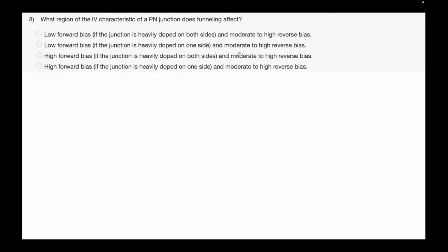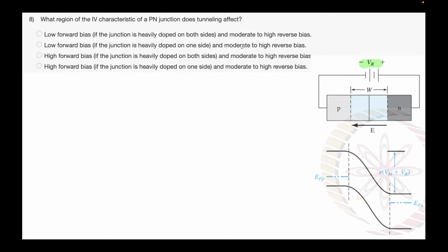Okay, so we had talked a bit about the reverse bias. This is the diagram from our previous sessions, and as you can see, when we apply reverse bias, the depletion width widens a little bit because now more mobile carriers are depleted near the boundary, otherwise neutral boundary, and you can see the effective band bending will be the built-in potential which was there at equilibrium plus the reverse bias VR that you are applying. Note the polarity that I'm taking.